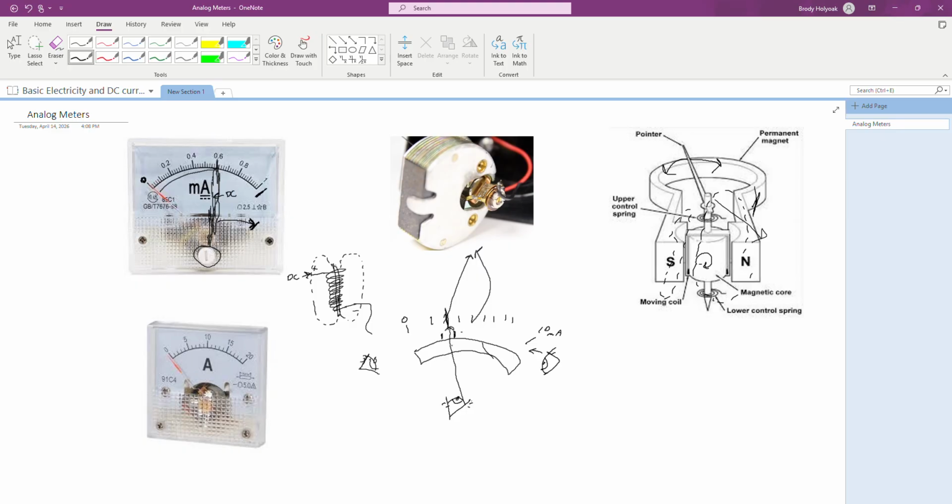And that reflection, that little mirror gets in there, so if you're looking at it right, everything should line up. If you're looking at it at a bad angle, the reflection, which I'll draw here in purple, will actually be sitting over here. So then you have to adjust your viewpoint so that this reflection and the needle line up, and then you can accurately measure what that is.